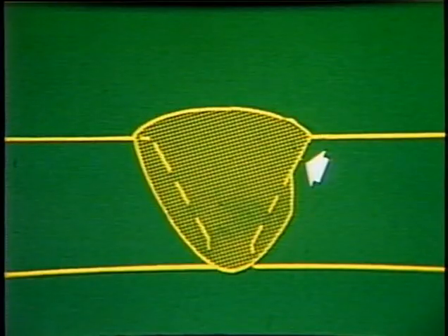Yet another type of internal weld discontinuity is incomplete fusion, which is the failure of the liquid weld metal to flow into and fuse the total face area of the joint. A discontinuity with similar causes is inadequate joint penetration, which is defined as penetration which is less than specified. This type of defect is located at the root of the weld.